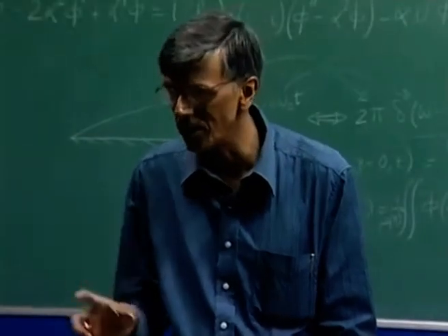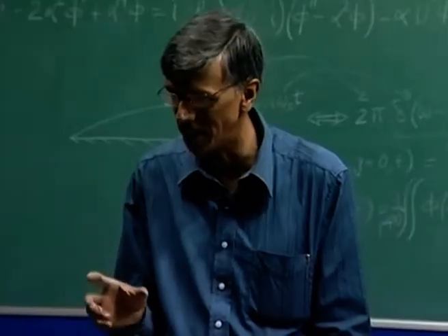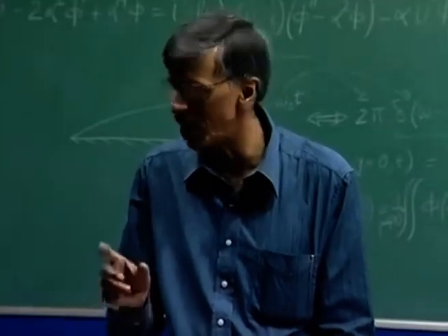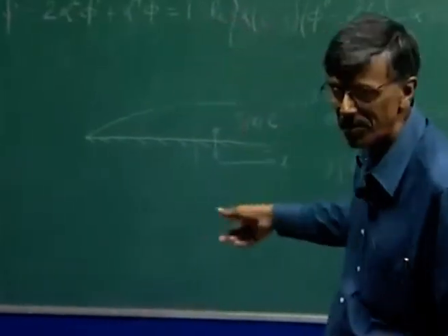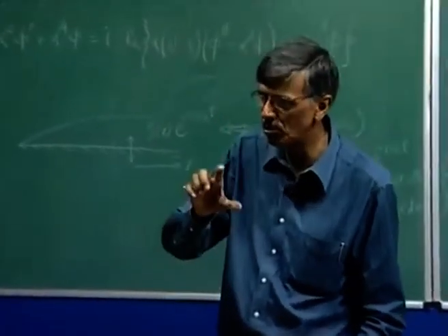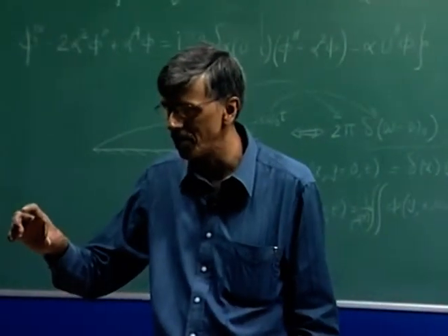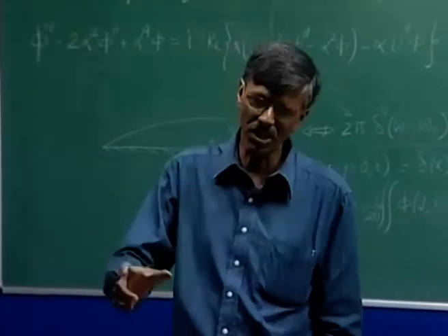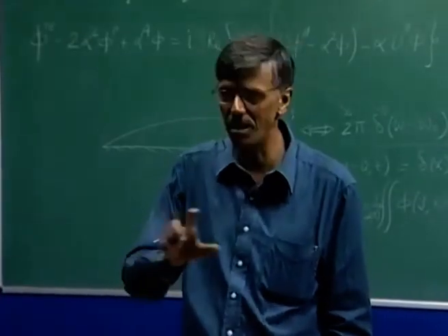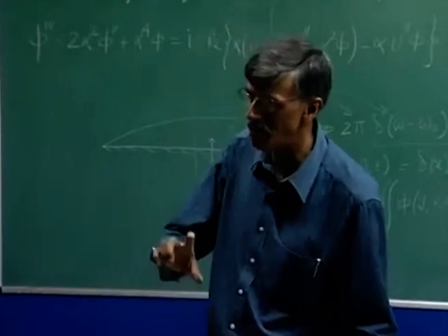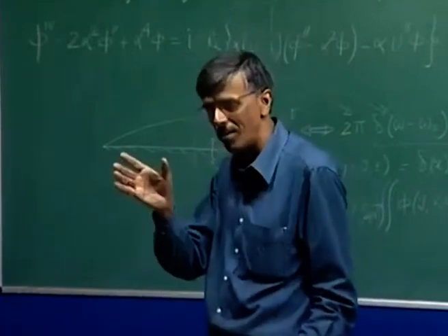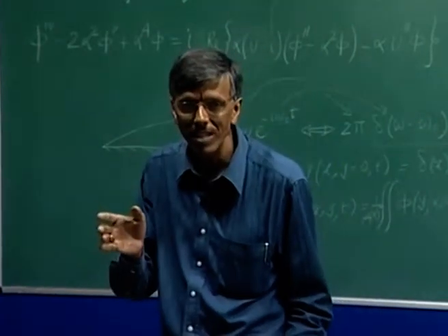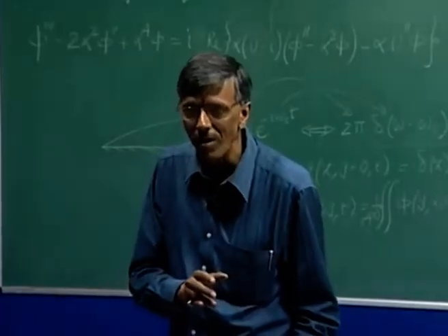There the contouring of the airfoil is done in such a manner, it is a passive device, you are not exciting a ribbon or anything of that kind, but you contour the profile in such a way that your pressure gradient is such, the curvature is such, that the background disturbances which are there do get less receptive. Because what happens?